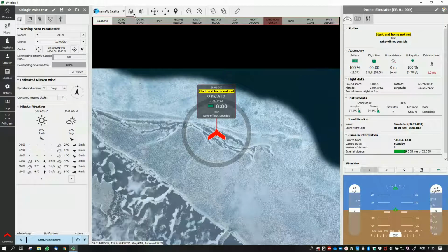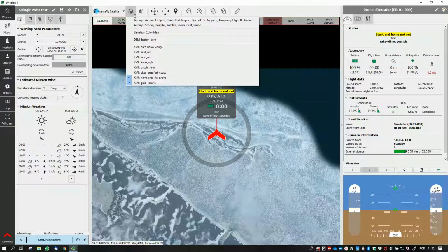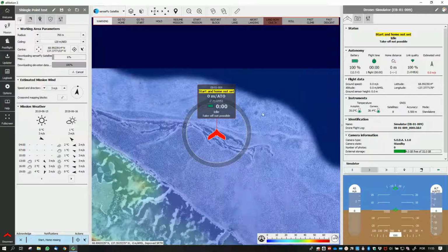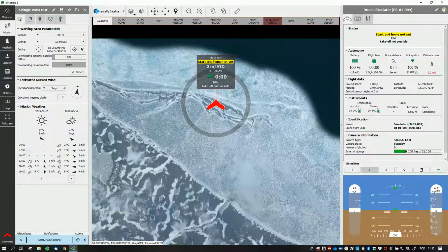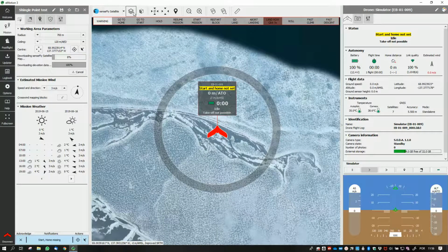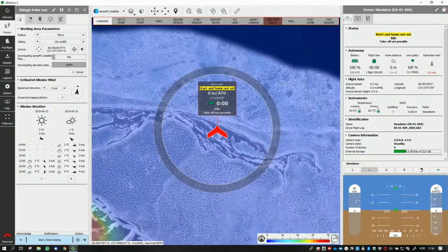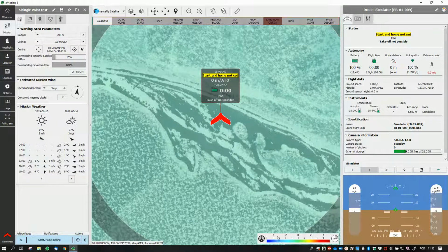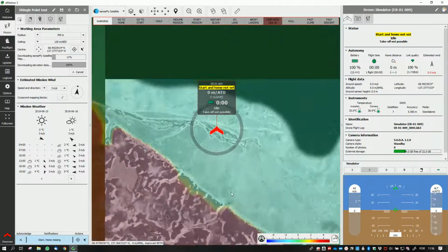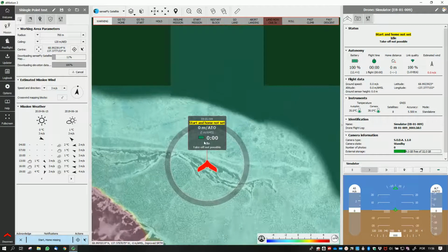If you want to have a look at the digital or at the elevation color map, you just click here and you have the background colors. It will not be an issue in this survey area because it's flat and it's at sea level. So elevation map, turn it on, turn it off, and you can tune in the elevation color ramp here. It will just stretch to the maximum and minimum of your working area. For instance, if you zoom in and you stretch, you see that it will stretch between -4 and 4 meters, and all the areas which are a bit higher will be in different color.